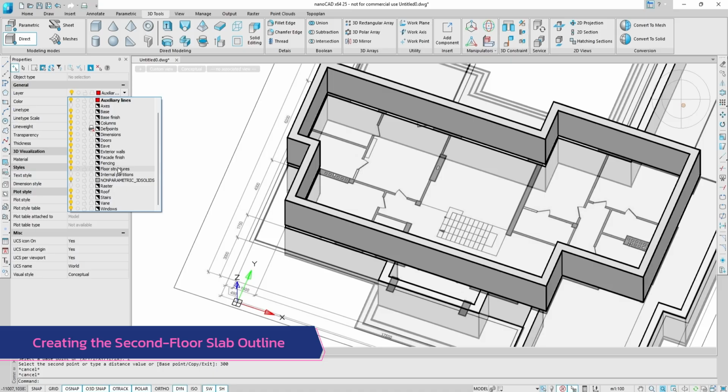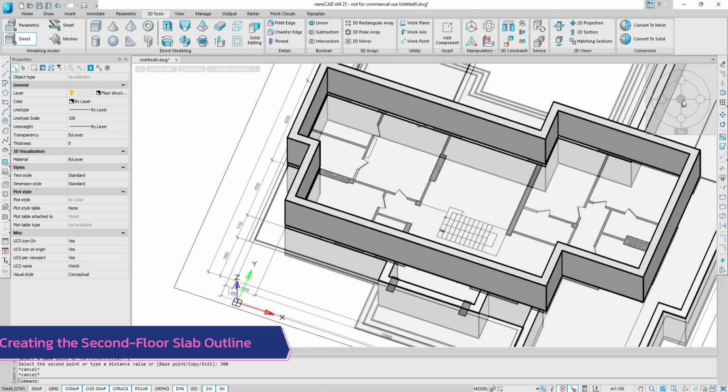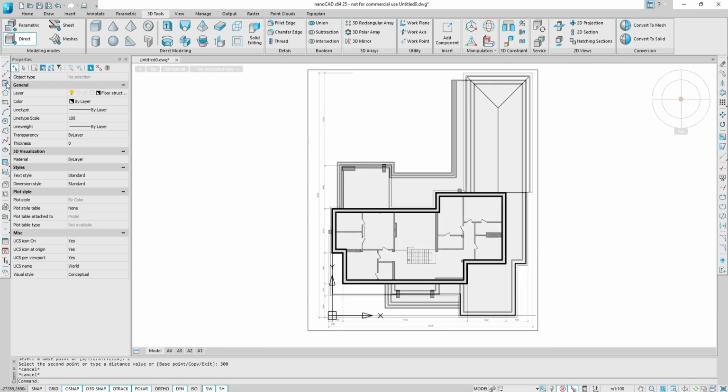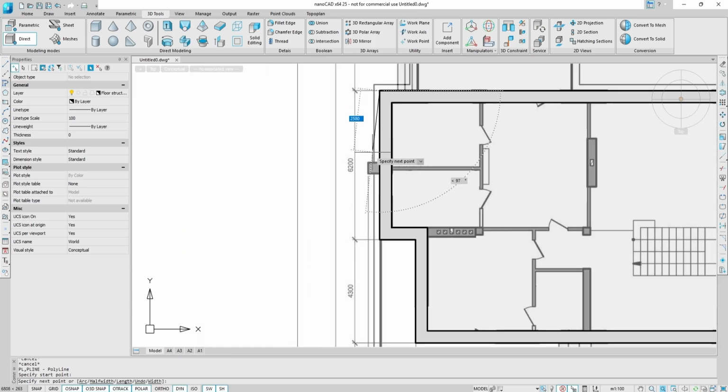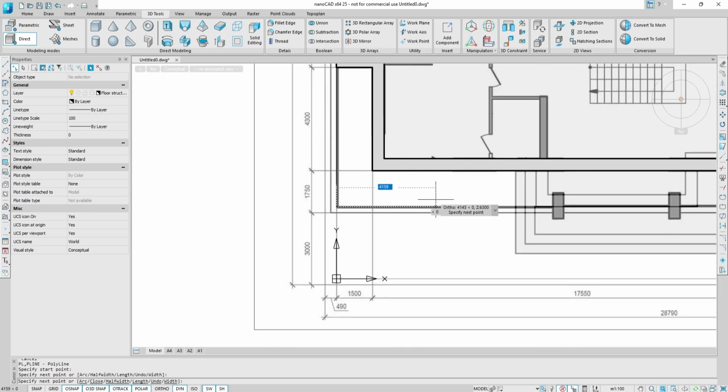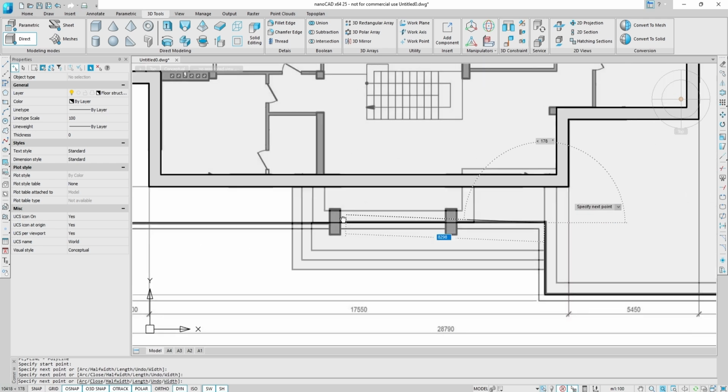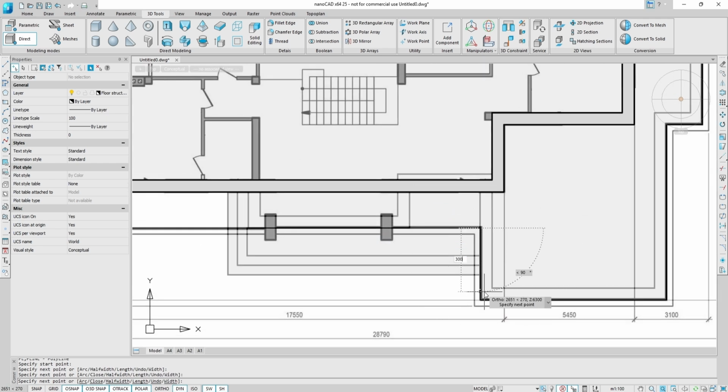Set the floor structures layer as the current layer. Activate the Polyline tool and start building the outline by anchoring the endpoint of the exterior wall. For further construction, use bindings or snaps, or set the length using the keyboard. Down 12,000. Right 18,050. Down 3,000. Right 7,800.